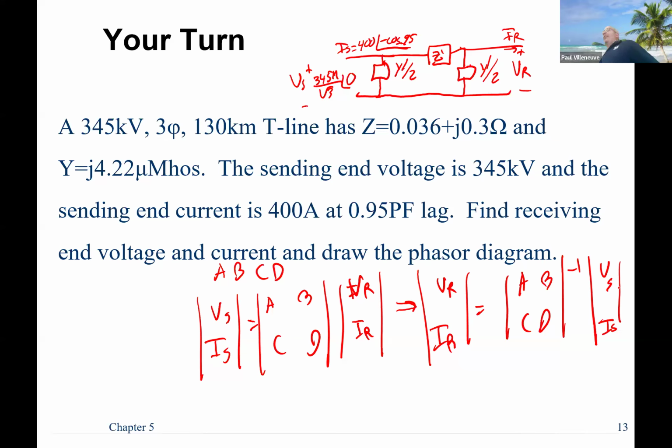You may want them to flow, like you probably don't want electrons to flow from Orrington up to New Brunswick, mainly because they might not be paying for that power. They might not agree to buy power from New England. So they're running at a really low value and they're getting power for free. And there are ways to control that automatically. But the concept is there are some cases when you never want power to flow in the reverse direction. But in AC world, you don't have any control over that. In DC you do, but in AC you don't.